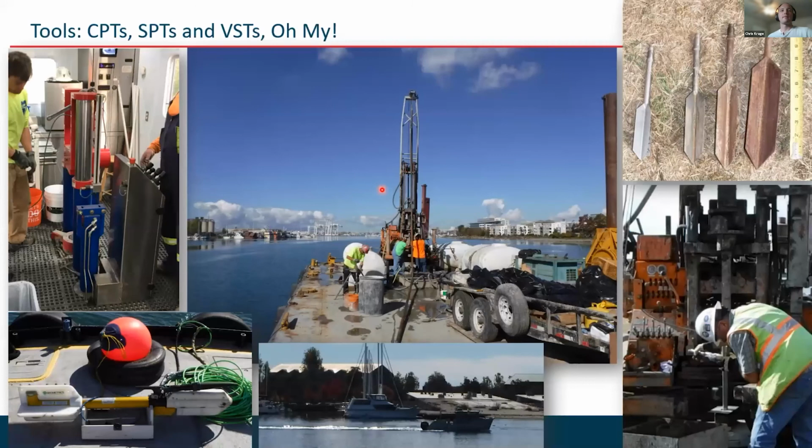So again, now we're going to go to the field. And we've got several different tools that were used on this project, including seismic CPT, as shown on the left here. In the middle is actually an overwater barge boring. So this is a traditional mud rotary drill rig on a barge that was used to collect information within the harbor. To the right here is vane shear testing.